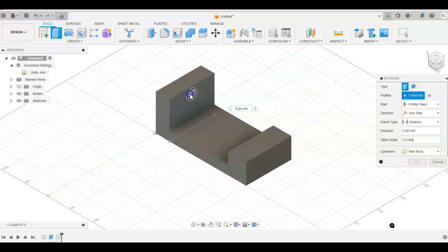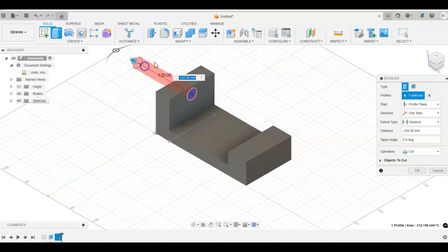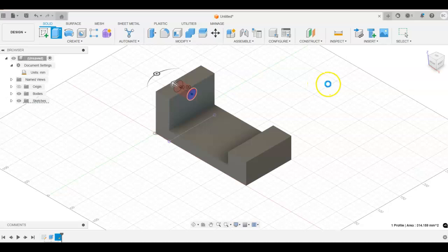I'm just going to select that shape. Now notice again, we can extrude this out to have it being projected, or I can go back in and set a dimensional extent. But in this case, rather than a distance, we know that it goes through all. So we want to complete, and we're cutting this out, and we're going to put a degree also. So that is that hole and that sketch.